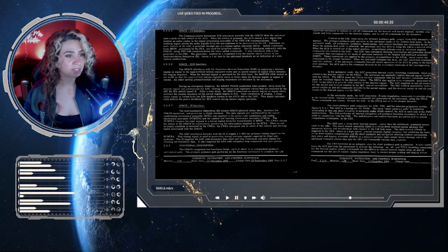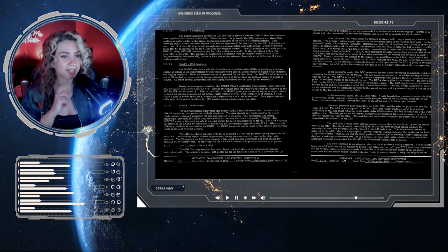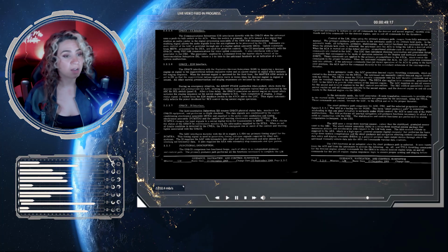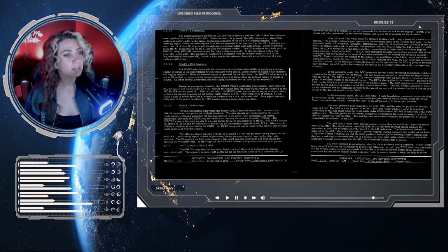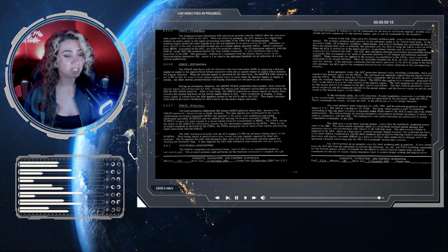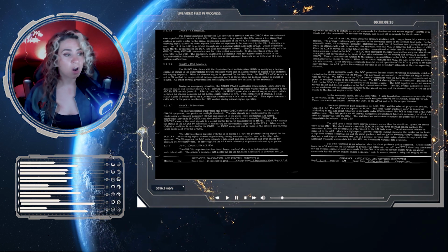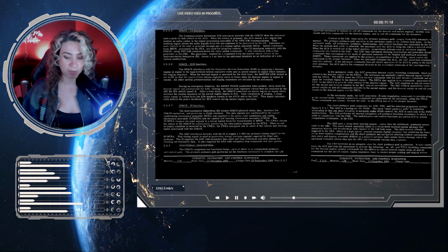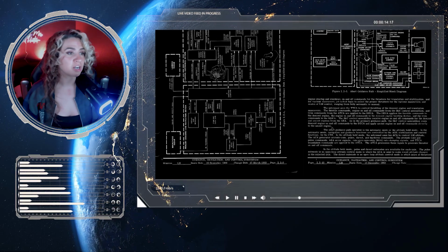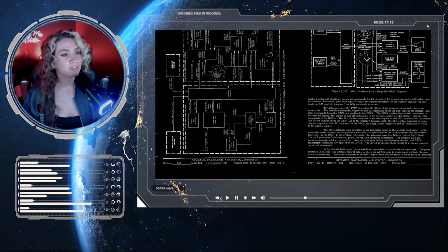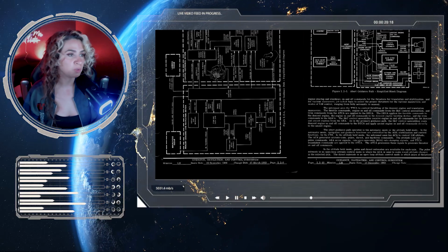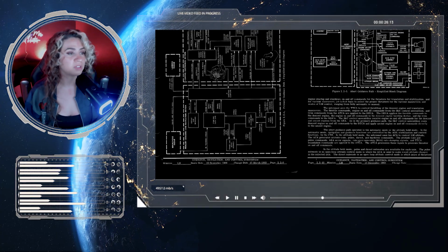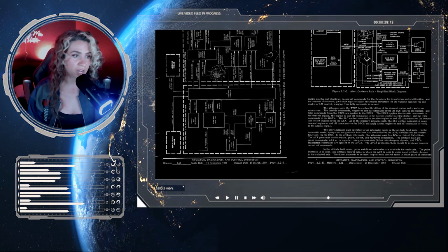The CES functions as an autopilot when the abort guidance path is selected. It takes inputs from the AGS and from the astronauts to provide the following: on, off, and TTCA throttling commands for the descent engine, gimbal commands for the GDAs to control descent engine trim, on and off commands for the ascent engine sequencer logic to ensure proper arming and staging before engine startup and shutdown, on and off commands for the thrusters for translation and stabilization and for various maneuvers, jet select logic to select the proper thrusters for the various maneuvers and modes of LM control, ranging from fully automatic to manual.